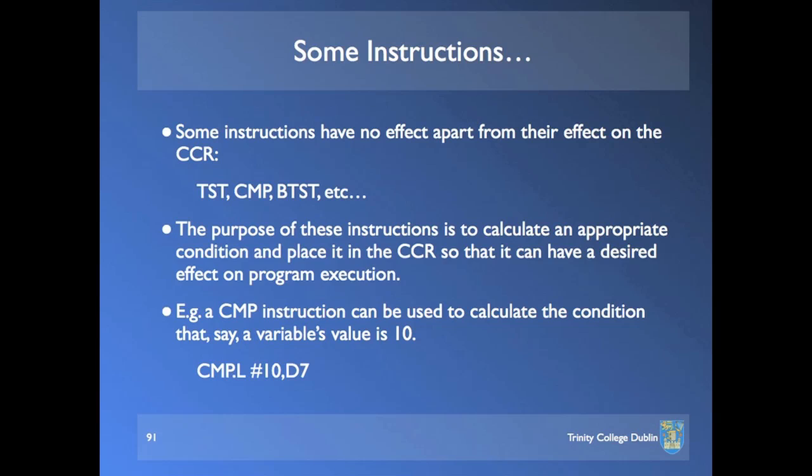Well, you're certainly affecting every bit at every second. So there's the actual overhead of turning on and off the latches and so on. But do you remember I was saying that in many modern machines you have these pipelines? Where you're executing this instruction, but you're also partly executing the next instruction, and maybe executing a bit of the one after it, speculatively. If you're executing an instruction now which sets the condition code register, and if the next instruction might depend on the condition code register, it means that this instruction has to complete before the next instruction